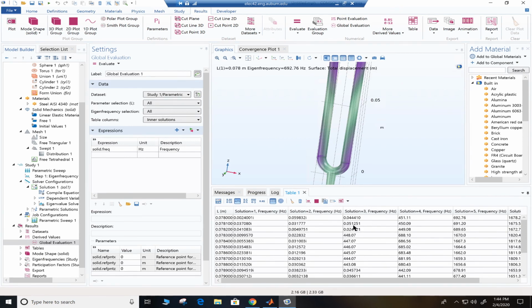So if we're looking at, for example, the one that's closest to 440 hertz, that's right here. See that? That's 440.13. That's good. And so it tells us that 0.0791 should be the length, if we want to build that type of tuning fork to have that kind of fundamental frequency. That should be the length of those two cylinders right there.